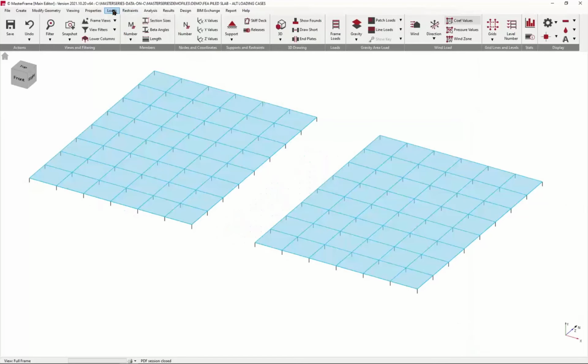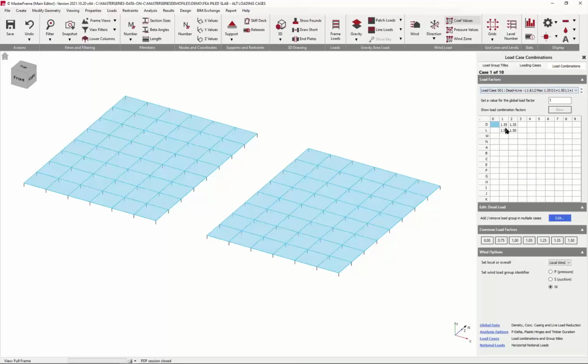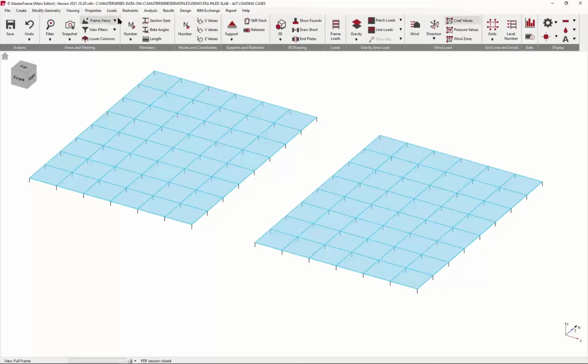What I also then do is under loading cases, very simply, I have loading combinations for D1 and L1, L1 only, L2 only, and then repeat it for the L3 and 4. I like to do all spans loaded on both L1 and 2 and then 3 and 4, just to make sure that nothing's been missed, because the values should be the same. And then in that direction, the patterning of that load. And you can do the same for your serviceability if you want. And that's how we did it.